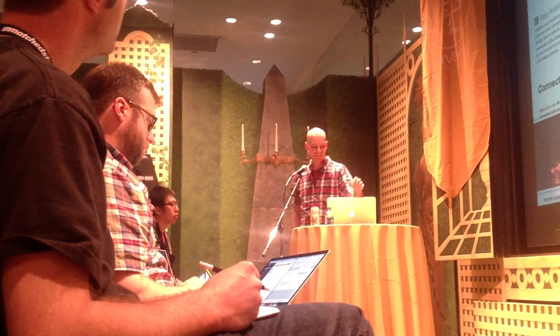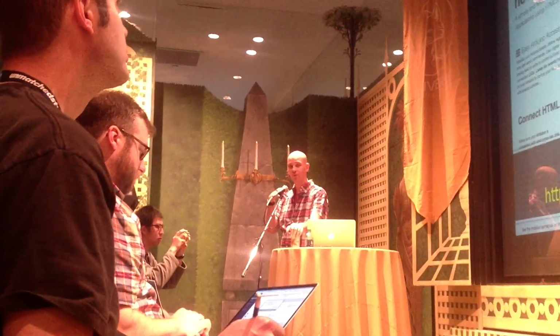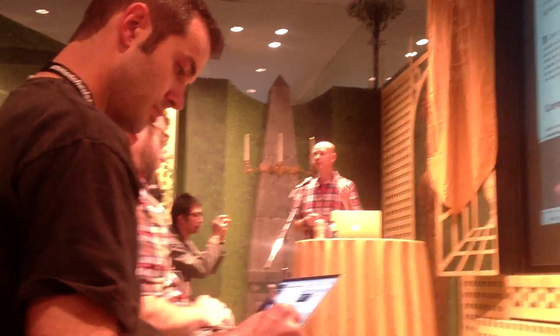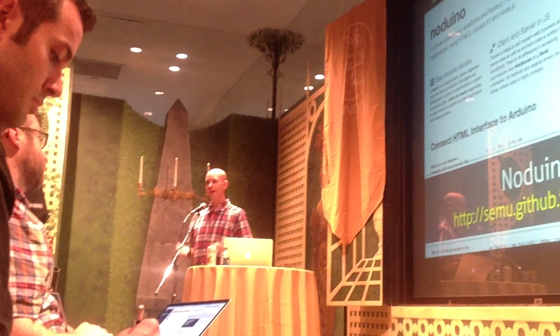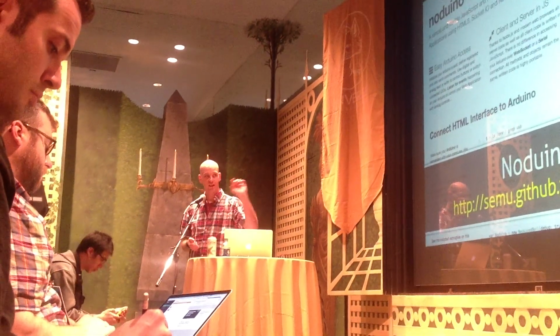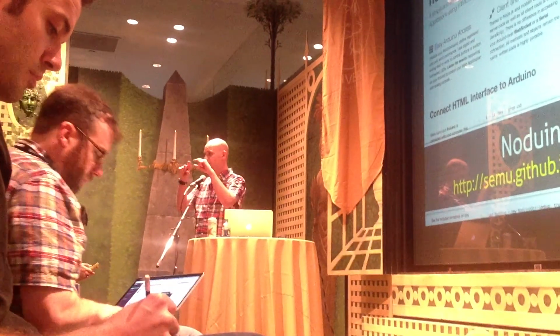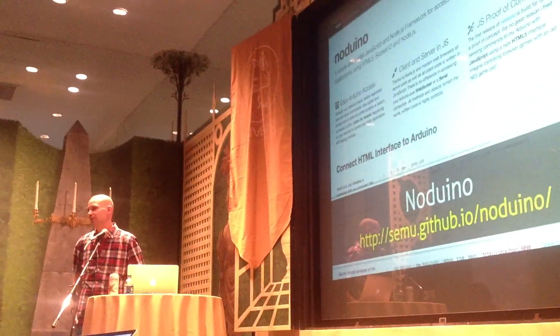Those are always fun. But you have to make sure you have security so that someone doesn't go in and hack and shoot them. But that's a really good integration, and it works with a kind of a variation on the Firmata example that we saw. So what you need to do in order to get this working is you download Arduino, and you can just download it from the GitHub repository here. Then you take what they call an Arduino file. It'll just be available in that repository, and push that up to the board as opposed to this Standard Firmata example. That's their transfer bridge that they built out. So that's really all it is, and then you can start working with this implementation, which is slightly different than Johnny-Five, but really easy as well.